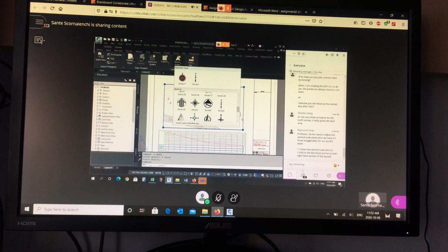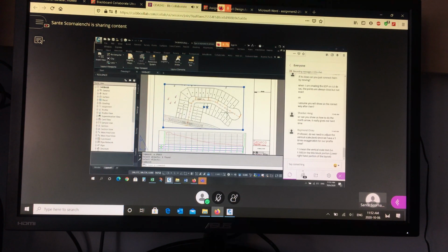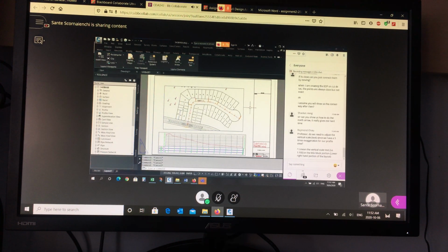Any north arrow of an appropriate size, and again, it's subjective, right? It can't be too big. If it's the first thing that catches your attention, it's too big. If you can't find it, it's too small. There's somewhere in between where it's an optimum size. Okay? But the simpler it is, the better. Remember, the focus is the engineering design, not the north arrow. So it shouldn't take away from the focus.